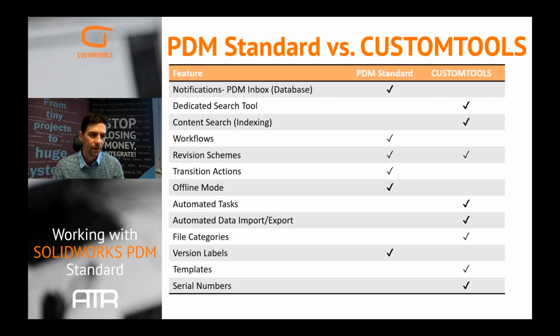And when we compare PDM Standard versus CustomTools, in addition to the SOLIDWORKS add-in, PDM Standard also has a File Explorer add-in, whereas CustomTools only provides an add-in for SOLIDWORKS. So we now only concentrate on the features that are inside SOLIDWORKS. And in this chart, I have only included main features that are available either in PDM Standard or in CustomTools to highlight differences. Furthermore, I haven't gone into tiny details of each and every feature.